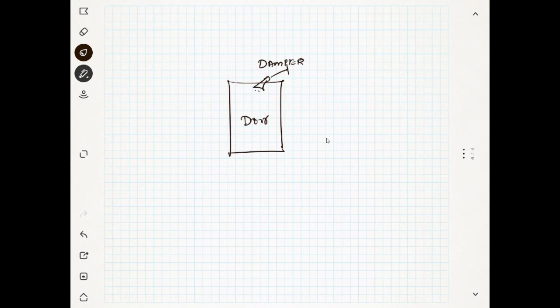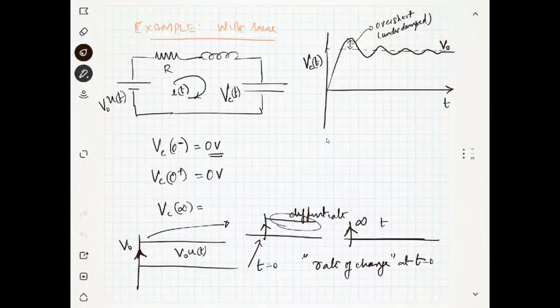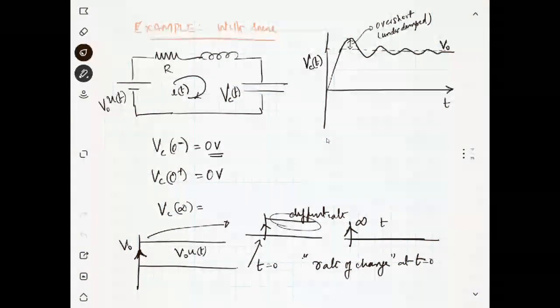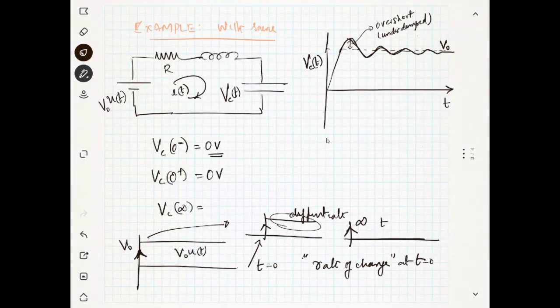But here you see this is moving. Here there is oscillation. That means it is moving freely. So there is no damping, or damping is below some level, less than 1. This is known as the damping coefficient, lambda, which is less than 1 mathematically. Inshallah, we will see the significance of this. So this is known as an underdamped system.